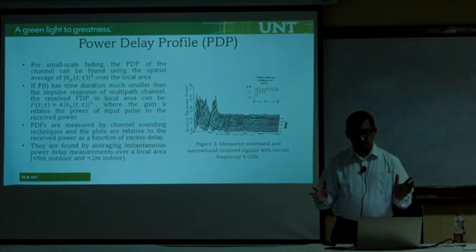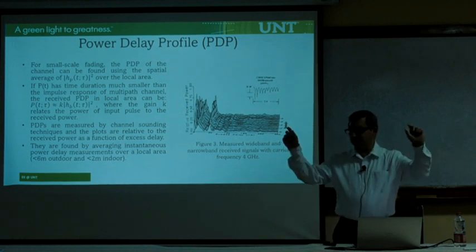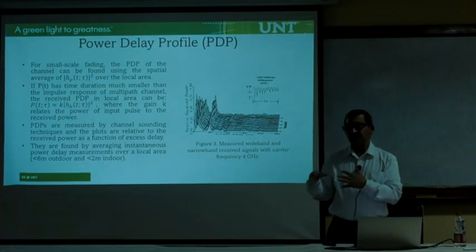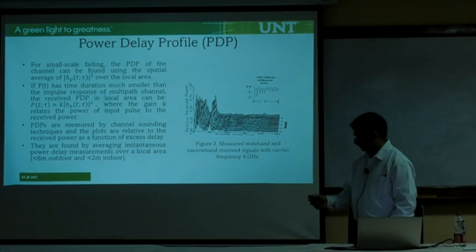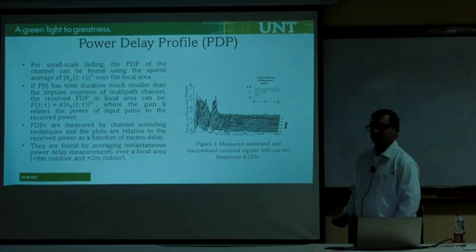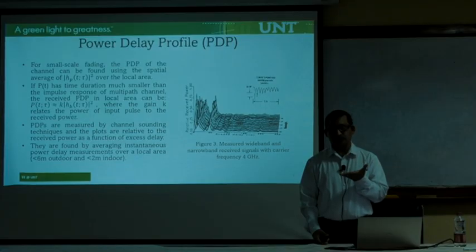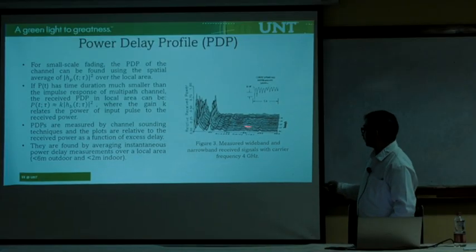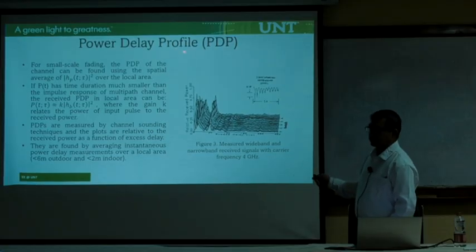So you create the environment and then decide the distance between a transmitter and receiver. Then all these reflections will happen. The tool will take care of it, and it will give you this data, this power delay profile. So all you need to do is measure the power delay profile and plot the graph corresponding to it, and that's what we can do through simulation.